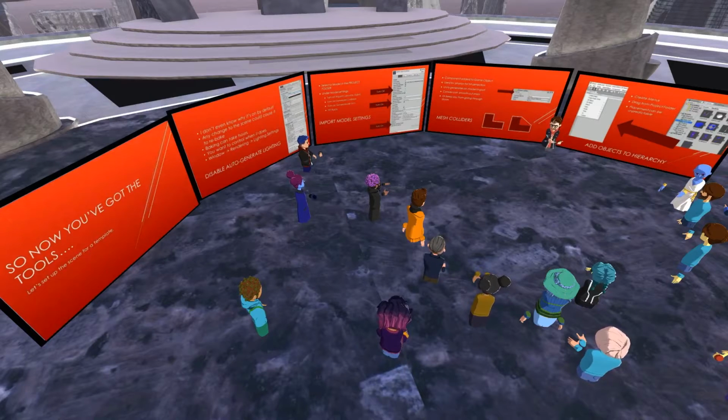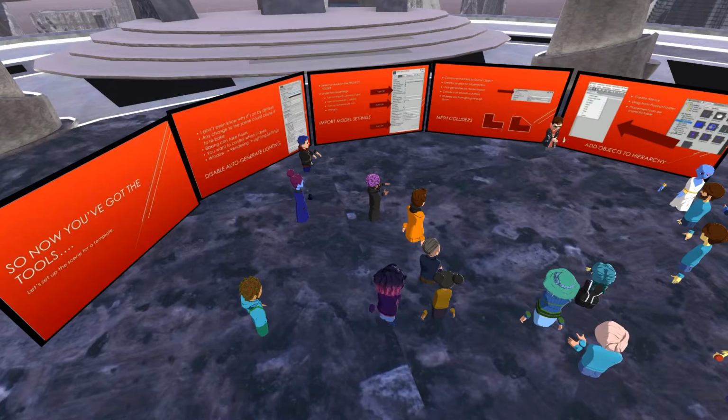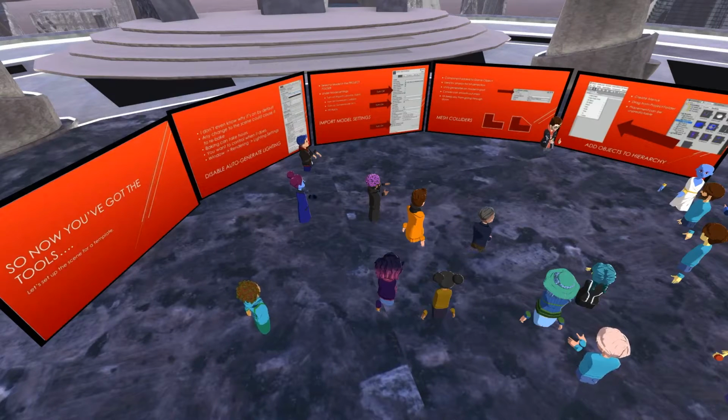able to go into. Let's say my stairs are curved, right? So I've got a circular set of stairs. I put a convex mesh collider on it. It's going to cut across that curve, and I won't be able to move my avatar inside the curve of those stairs because they'll be sort of encased in this shrink-wrapped collider. I may still be able to smoothly go up it, but I won't be able to go inside of it.